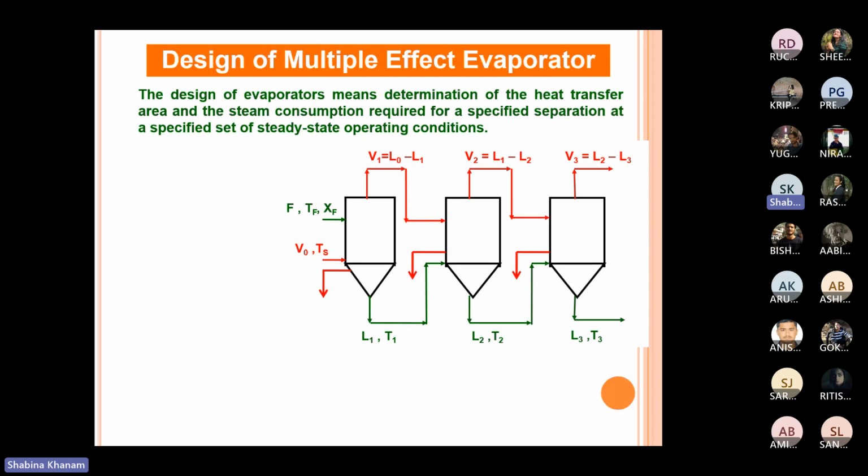Now, to start the design of the multiple effect evaporator, we will first derive the governing equations related to the evaporators. Let's see that. For the first effect, to derive the governing equation, we need mass and energy balance. Wherever I draw a balance, I usually put an envelope around it.